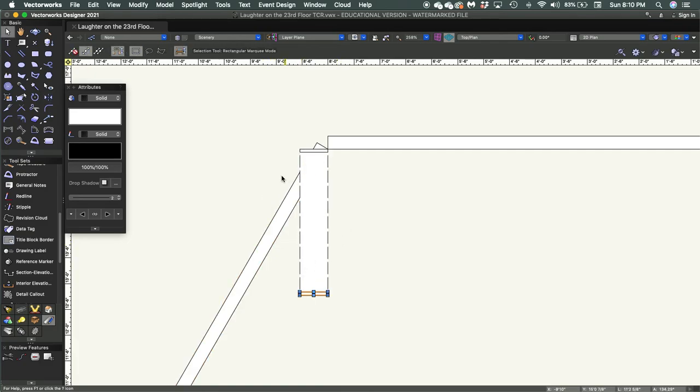Next thing we're going to do is create another rectangle that represents the actual door. It's going to be 1 inch thick, so we'll activate our rectangle. We're going to start it just inside this door jamb, and we'll bring it all the way down to this one and tab into our display bar and tell it that it's going to be -1, so it's 1 inch thick inside of the jambs. And we'll click that to complete.